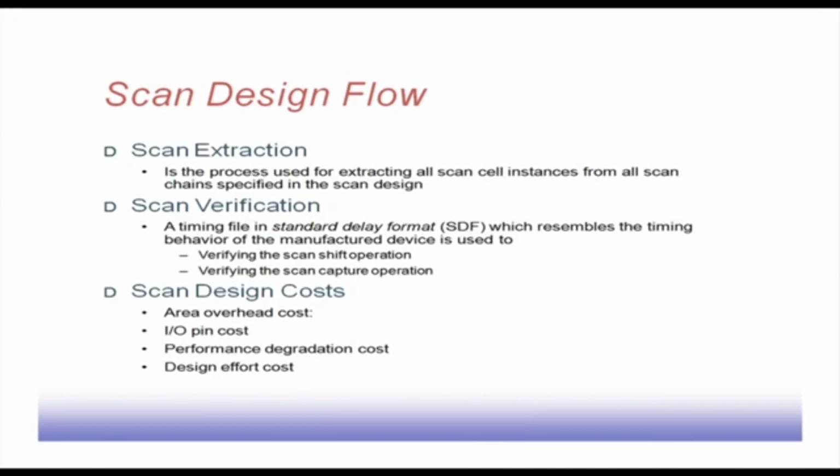Then the performance degradation cost. Performance gets degraded because some extra circuitry has been added, which may come into the critical path of the design, so delay will increase. And then design effort cost. That is the extra amount of man hours and effort that needs to be put in, so that this scan insertion is done properly and testing can be carried out. That is another issue.